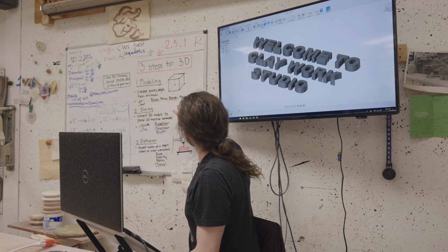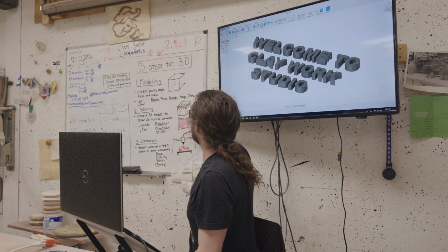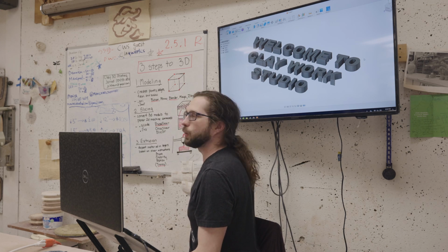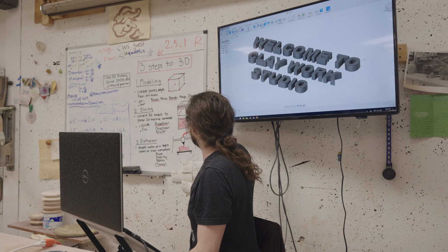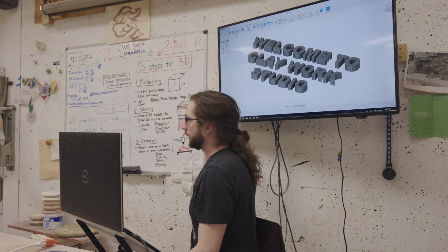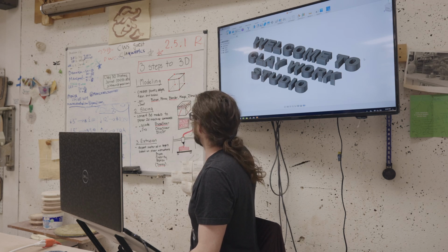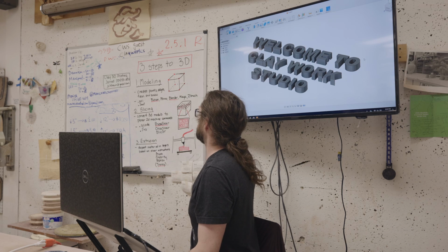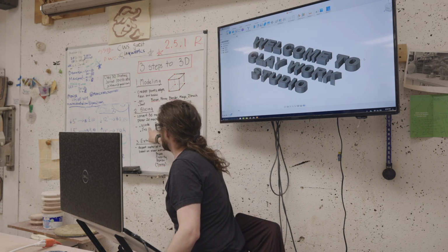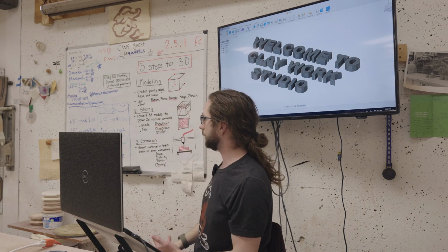So that's the role of the slicer, and what it is outputting is what ends up being a giant text file of all of the commands that the 3D printer needs to follow in order to make these slices come out correctly. It's more human readable than an STL. If you open up these G-code files, that's what it usually produces, you'll see a bunch of commands.